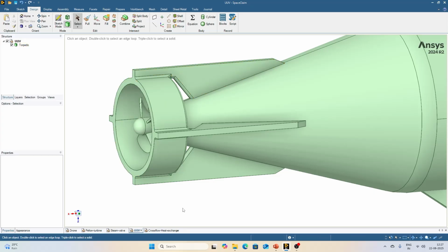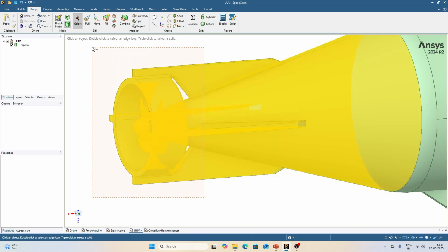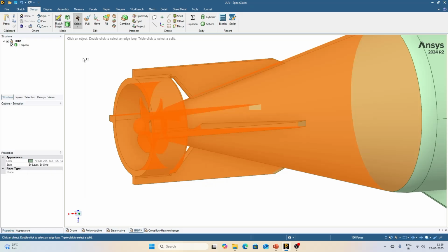We have learned about a box selection method by creating a box from left to right. There is one more box selection option. Let's see what happens if we reverse the box creation. If we create the box from right to left, then you will notice that all those geometries or entities which are inside the box completely or even partially will get selected. You can see that the extent of the box is just at the end, but all other surfaces which are outside the box are also selected. But some of the surfaces were partially inside the box, so all of those surfaces will be selected.